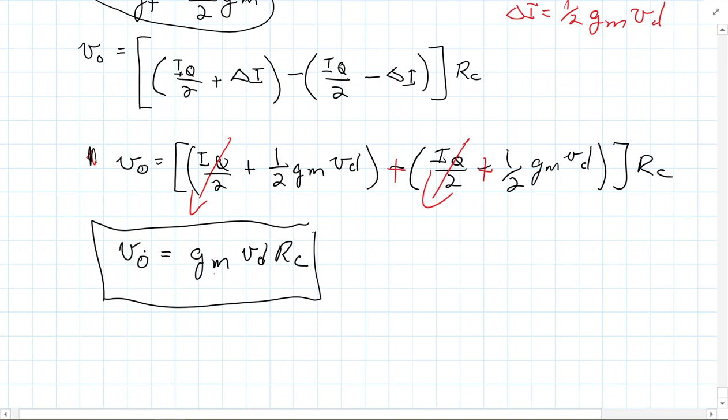So what are we amplifying here? And this should look pretty similar to us if we think about a voltage gain here. If we think about the differential voltage gain being V out over the differential voltage, we get that this is GM RC. And you should say, hey, this actually looks pretty familiar to me. This is what we had for common emitter amplifiers.